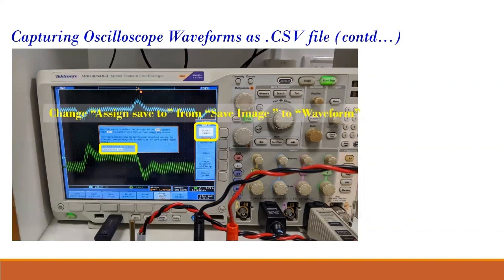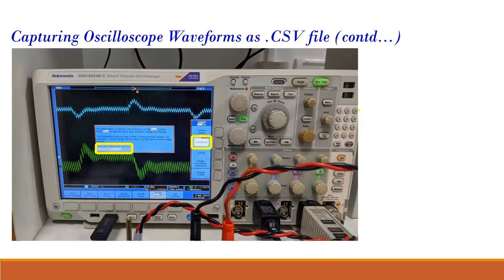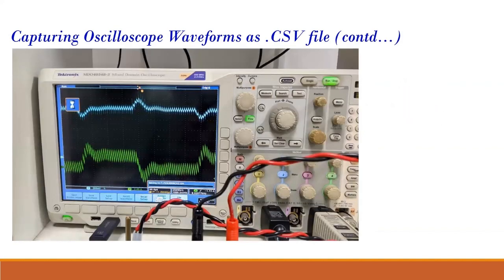You can save the screen image. If you say that you want to save the waveform, then it will be a .csv file, which is your Excel file. It will take some time to save. It will not happen instantaneously, and that will be seen over here. Okay, this is done.